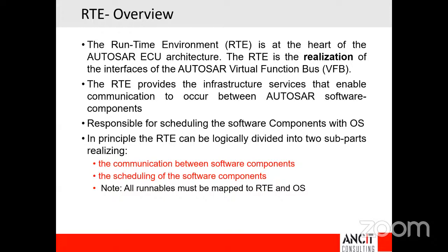It will be the list of variables, which could be any type of variable, including structures and arrays. You declare all these variables, and you tell which software component has to talk to which other software component, and which variable has to be passed from what to do. This high level design is what we call the virtual function bus design.